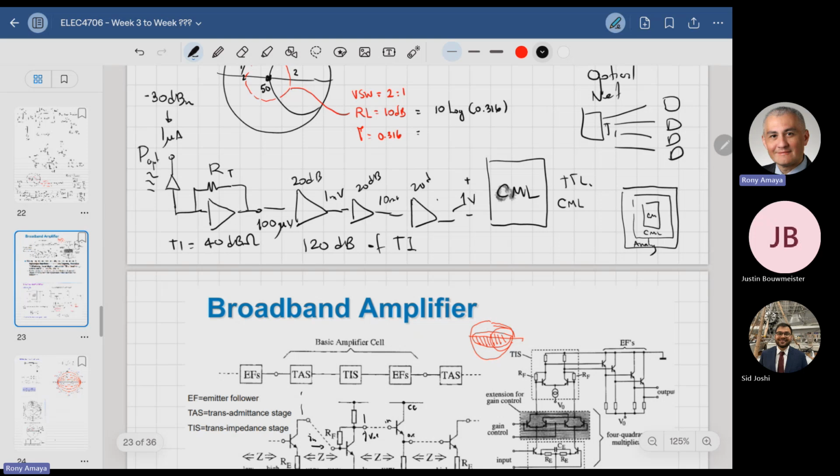To comply with standard chipsets, you have to deliver the CML amplitude level. And that's where you need to amplify the signal. Now, of course, this is not very easy to do, because with a 120 dB gain amplifier, what could go wrong? That's like taking a stick of dynamite and barbecuing with it, and seeing what happens. Hopefully, you're not going to. It's a very unstable circuit. There's a lot of things that could go wrong with it.